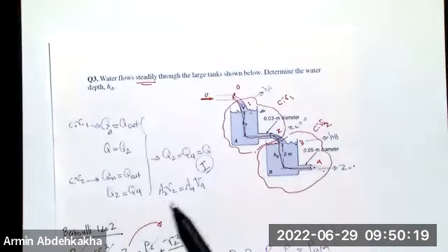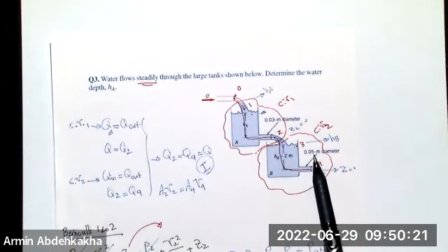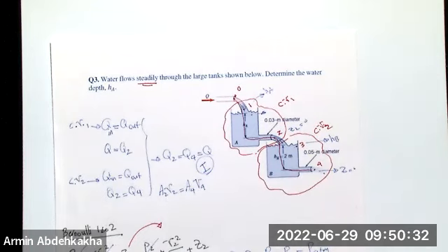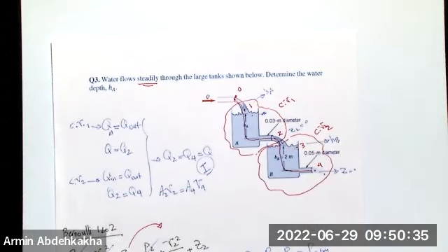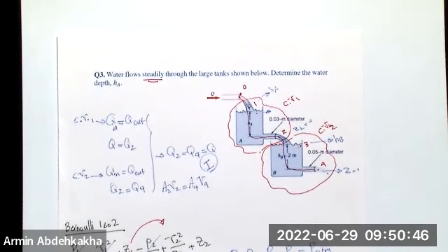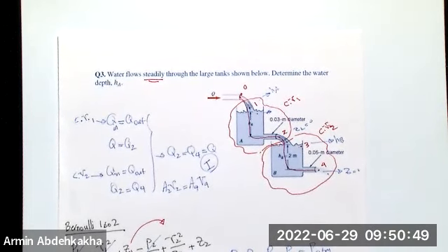Because A2 and A4 are constant numbers, based on the diameter, you can find the relation between V2 and V4. Again, if this equation gives you 2 more unknowns, for example, if the Ds are not given, then this is not an equation you can use, because adding one more equation that brings one more unknown would be a closure problem. If you add more equations and they give you more unknowns, nothing is going to change. One equation added, at the same time one unknown is added.